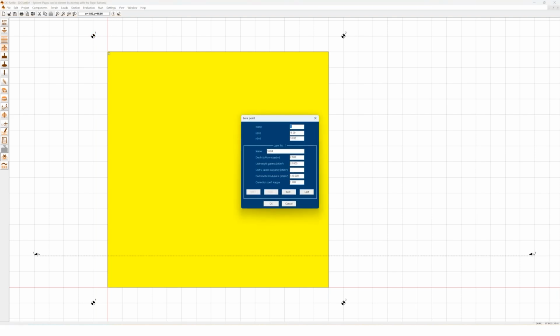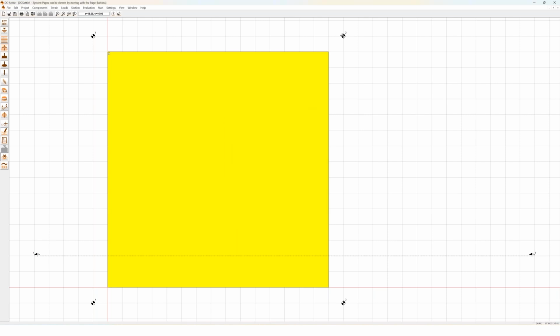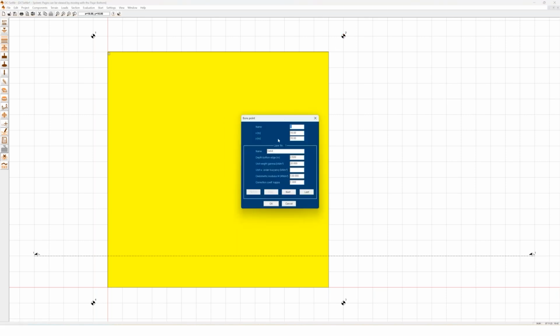But first we add the layer thicknesses. We double click on the bore points. This is bore point 1 with greater silt thickness. Sand is just 80 centimeters here. Next is silt, which is 8.5 meters. Next, gravel, we must not do anything here. We say apply.